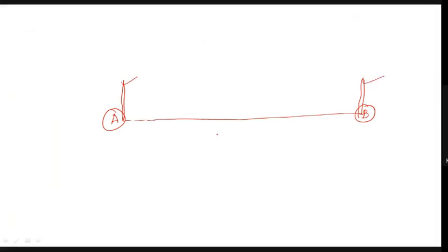Now I want to establish the intermediate point at, say, here, wherever you need. Here there will be one person, if I draw like this, standing 2 meters away from station A, and there will be another person who will be holding the ranging rod.